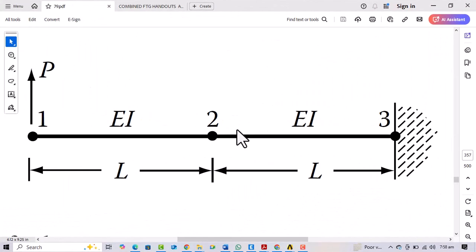In this video, we are going to see how we analyze a cantilevered beam in ANSYS APDL. This is our beam. It is basically a rectangular beam whose width is 1 meter and whose depth is 2 meters. The modulus of elasticity value we will be using will be 1000, and the P value is a unit load acting in the upward direction, and the length is 5 meters. This beam is fixed at node 3 and a point load is acting in the vertical direction at node 1.